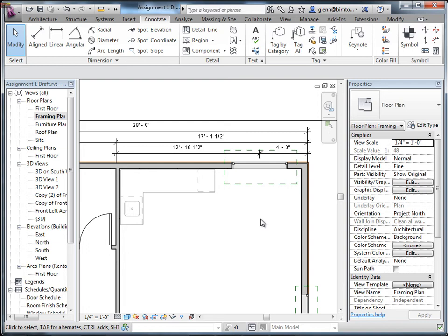So let's see if we can clean this up there. Let's see what your dimension is. That one, they're clearing up the wall. Okay, and what are we trying to do? Well, you want to resize the length? Oh, what we have to do for that is actually you wouldn't choose that wall, you choose one of the end walls because it's going to stretch that way. So if you want to make that wall longer, it's going to sound weird. What you actually have to do is move that wall to make that wall longer. See, it's a weird relation. It's backwards.